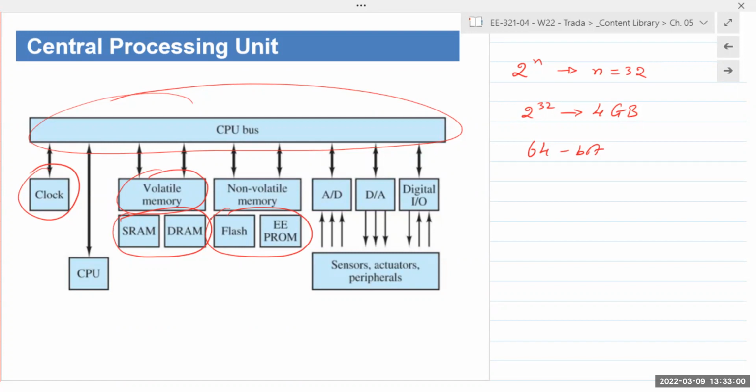Then came the programmable ROMs, meaning you could take the chip, program it in-house and use it for your application, but you could not reuse it once you programmed it. Then came erasable PROMs, which had a small window where you could shine UV light through that window and erase the chip and reprogram it again. And then came EEPROM, which is electrically erasable, programmable read-only memory. And those are the kinds that are still used in some tools to this day.